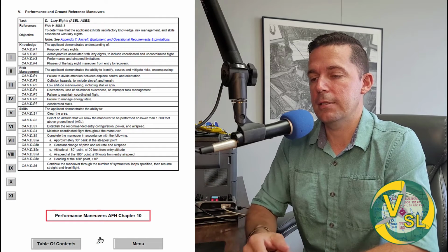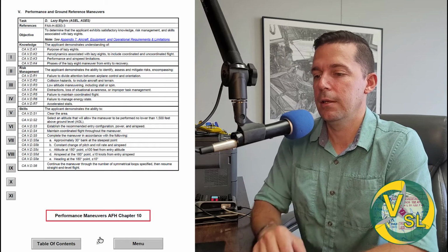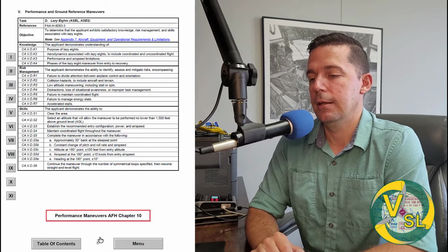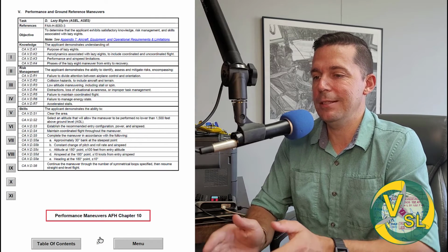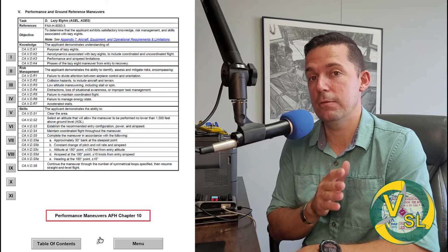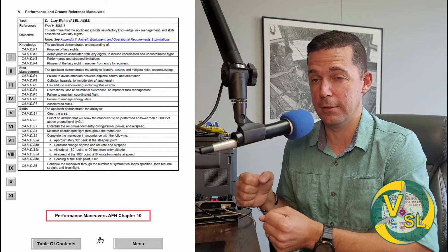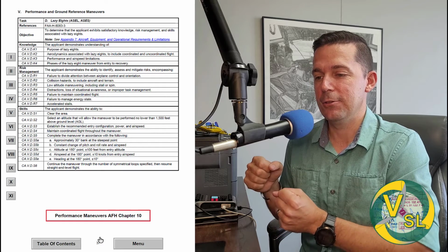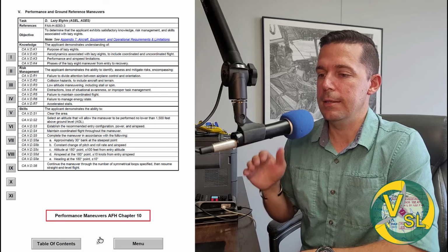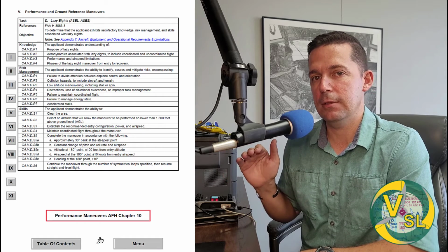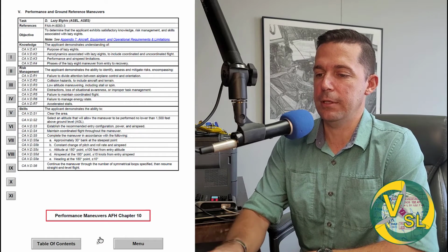When I'm teaching aerobatics, this is one of the first maneuvers that I do, lazy 8s, but we do them at 90 degrees of bank instead of 30 degrees of bank. But it's a fun maneuver to do, even with this 30 degrees of bank. It should be just a nice, lazy maneuver, right? You're not in the Top Gun movie here. You're just letting the energy carry you through these turns, and then you're aiming for that specific heading and airspeed and altitude points to be within tolerance there.